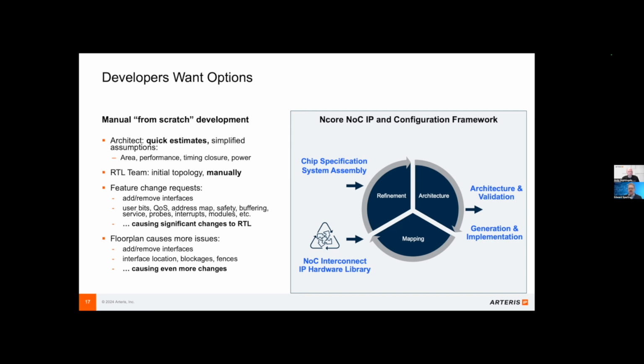Where do problems typically come in here? What do design engineers really need to think about when they're putting this together? Yeah, so floor plan is absolutely key to, of course, the layout team. Every time that interfaces with large numbers of wires are added or removed, or the locations are changed, or a memory resizes, the blockages in the layout actually change size, and the amount of free space that you have to flow your interconnect wires through changes. And this is causing real headaches unless you have some understanding of floor plan when you design your NoC. It can easily be reconfigured or respun as these blockages, the size of the area on die, change as the design changes.